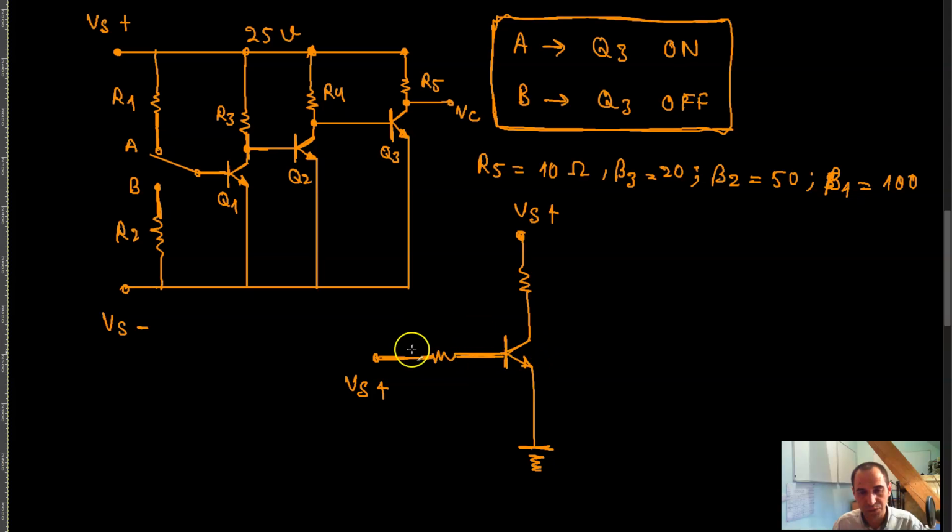So this transistor is an NPN bipolar junction transistor. The way that it works is that this is your I of B, and this is your I of C. There is this relationship: I of C to I of B is equal to beta. This beta is set for every transistor, at least for different currents and voltages.